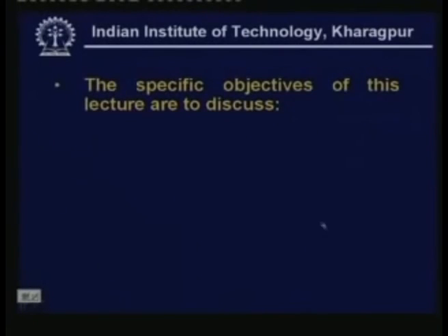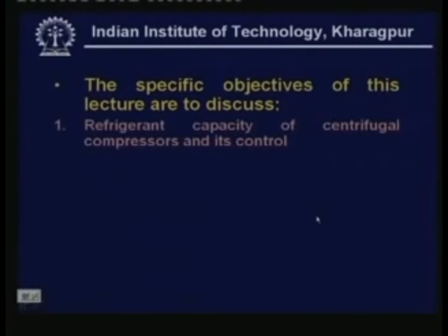Welcome back. This lecture is a continuation of the earlier lecture, wherein I introduced centrifugal compressors. In this lecture, I shall discuss the performance aspects of centrifugal compressors and briefly discuss the commercial centrifugal machines. The specific objectives of this particular lecture are to discuss refrigerant capacity of centrifugal compressors and how to control the refrigerant capacity,